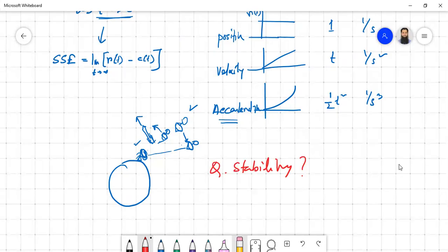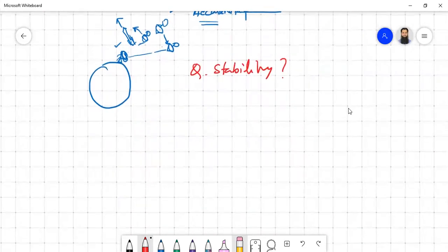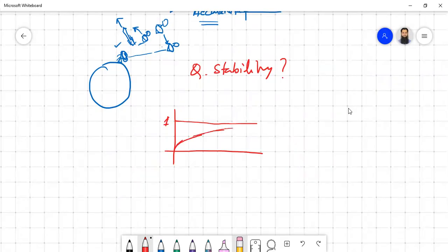Say this is a step input. Our prescribed test input is a step of one. For the step, we know that our output should be one. We're just assuming this is our one amplitude line. Now there are only two possibilities. One possibility is that after some time, when the transient has vanished, the output eventually merges with our input. In this particular case, we call this a zero steady state error.